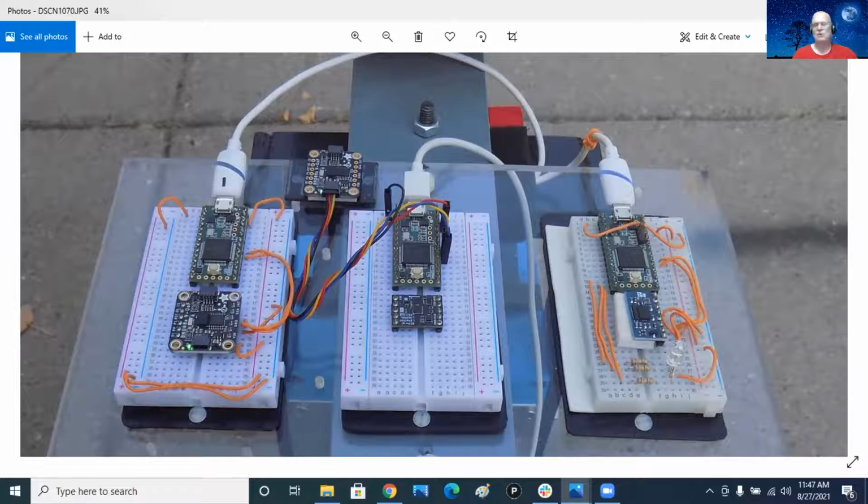And so in the house, it seemed to be happy, but out in the yard, I can't get it to work. And also on my BNO055, when I was doing the calibration, I'd go through and do all the calibration, read the values out and store them locally in the EEPROM of the Teensy here, so next time you start up, you can read those values and load them into the chip. And that seemed to be immediately coming up with a calibration status of 3, or I just had to wiggle it a little bit, just so it could see any small amount of movement, and then it would lock on and say it had a calibration status of 3.